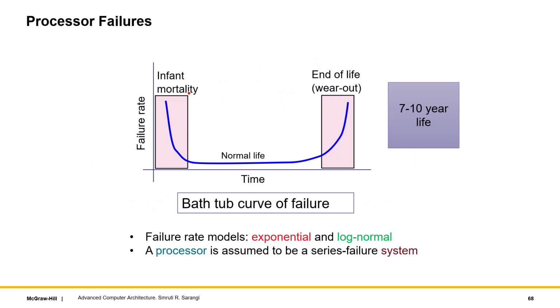If you look at processor failures because of a combination of all of these mechanisms, hard errors, which is the end point of aging. In aging, of course, we didn't discuss the interconnect models, but in hard errors, we discussed the interconnect models. Aging was more about a reduction in a transistor's life. But in any case, if we take the sum total of everything, we will see that there is this infant mortality phase, which means that some processors which have design defects, let's say a lot of variation, would fail at the time of burn-in itself.